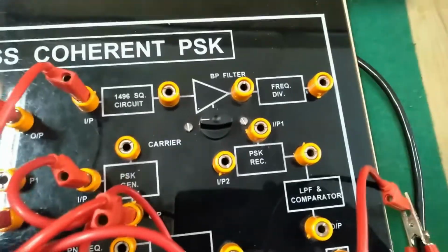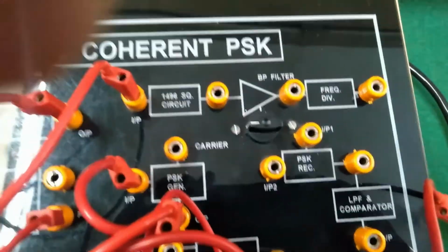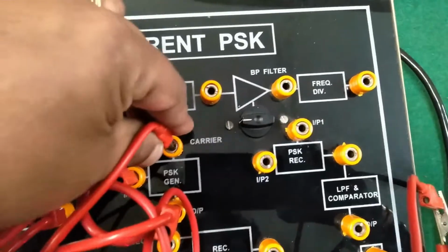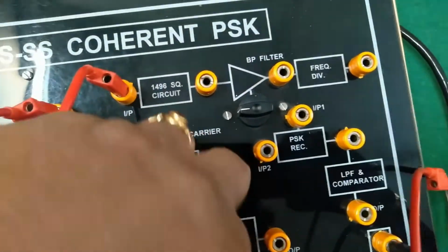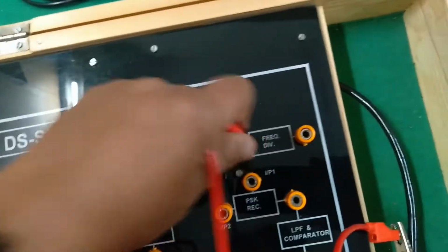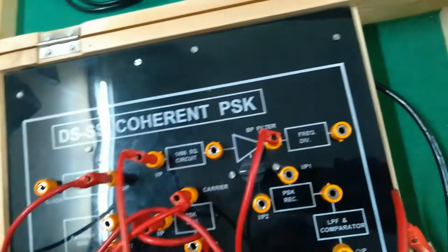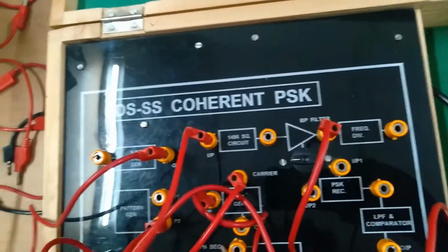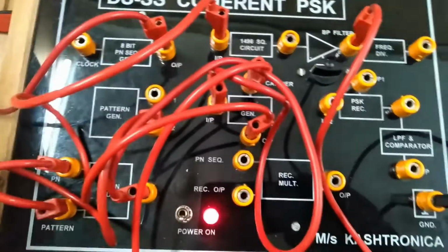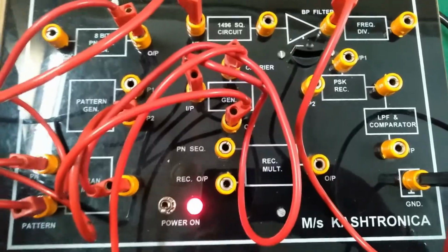Once again, if you want to check the carrier frequency, here it is 20k, and here it should be 40k. So if you want to check, we can check the carrier frequency itself. I'm connecting the carrier and the band pass filter together, correct? I'll check which channel it is connected to. I'm connecting channel 1 as the carrier and the second as the band pass filter output, which is going to be twice the carrier component, right?